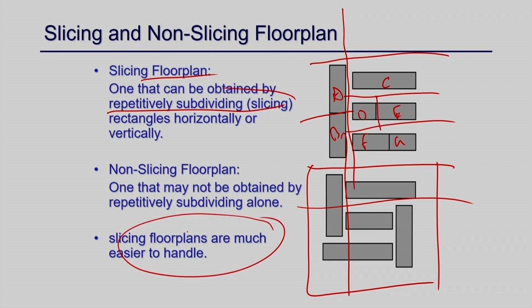In such a way you make the connections so that you can get a sliceable floor plan, and we will see that a sliceable floor plan is easy to handle for placement, routing, and all other components. So, usually the kind of floor plan we try to generate is sliceable, right. Let me repeat: sliceable is something where we can bipartition each sub-component at a time to generate your layout plan, in any order, horizontally or vertically. Okay. So, these are some terminology that you should be aware of during floor planning.